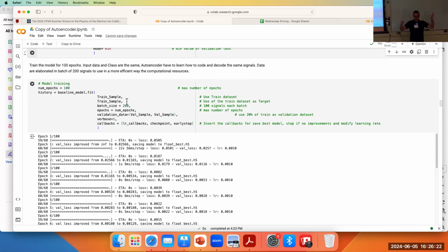I want to be sure that going through my autoencoder, I have my waveform, and I compare it with the same waveform at the end. I want them to be identical, or as much as they can. The 48 numbers that define the waveform at the beginning and at the end should be close to equal. This is an average. We are summing up the error of each of them, so it's not exactly that each sample will be exactly the same as the other sample. Okay, it's on average.